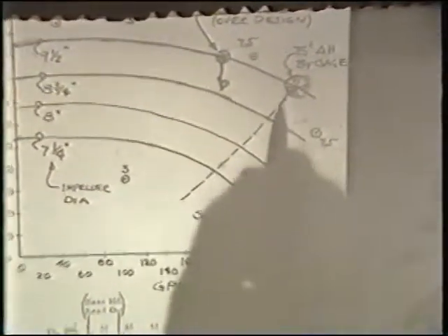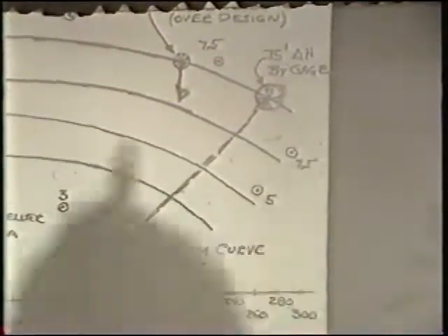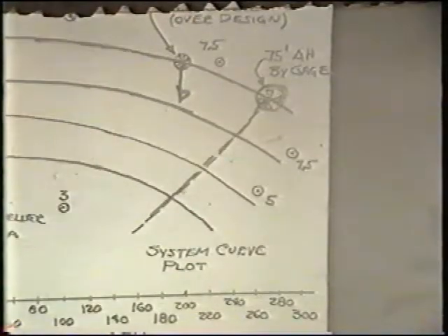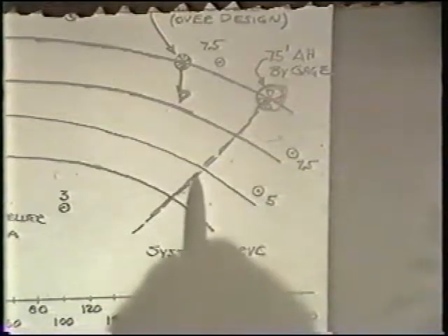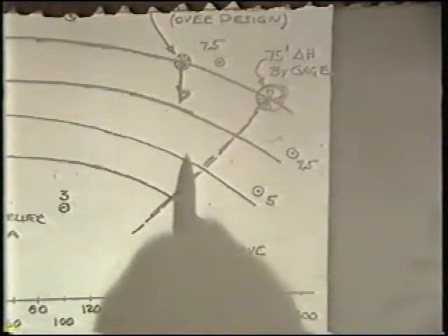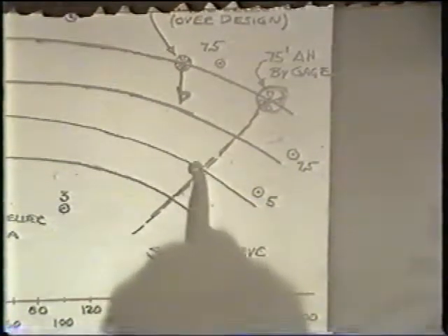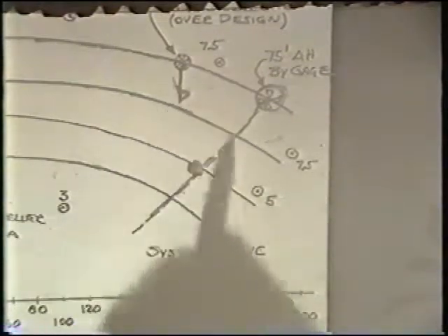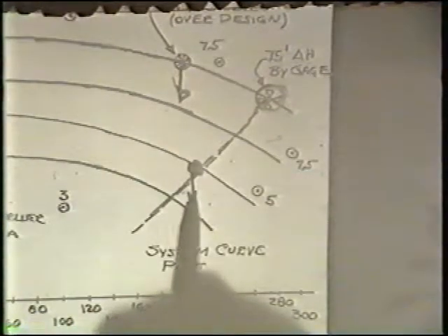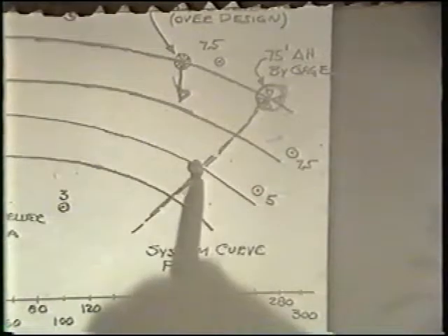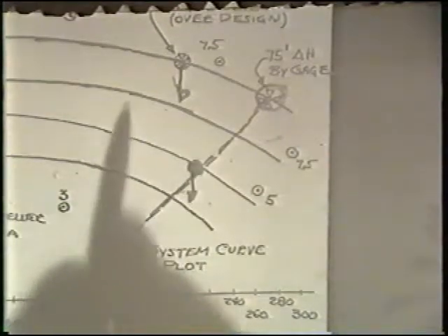We can then describe a system curve through the series of impellers allied with that particular pump and establish in a very simple way the impeller diameter that will match the flow rate need in terms of impeller size.